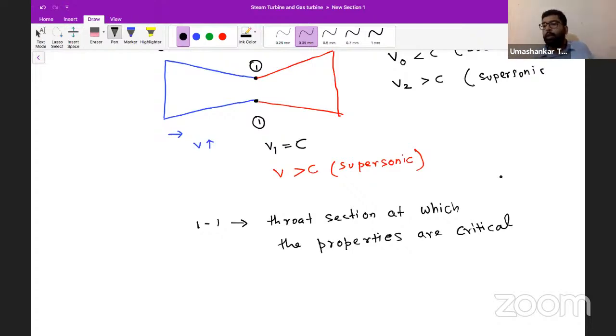So what is the conclusion of all this? The conclusion is what you must understand: before entering the moving blade, what shall be the design of the passage of the nozzle? Either it should be converging, or diverging, or converging plus constant cross section, or converging then diverging cross section. So when to use which kind of nozzle must be clear up to this point.